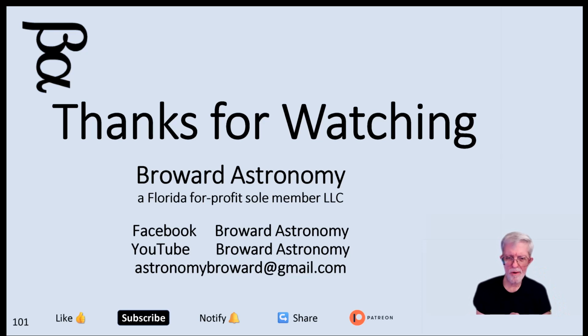But since I'm recording the audio at 44 kilohertz, that guy Nyquist comes into play. If I want to record something that's 1.2 kilohertz off and on, then all I need is 2.4 kilohertz of recording, and I have 44 kilohertz of recording. So you get to see the laser off, on, off, on, but it's only there when I have the RGB channel value greater than 0, where you actually see what would be the light output, and you see that gapping in the signal.